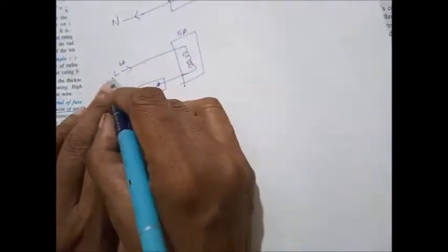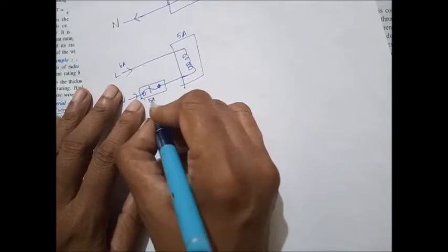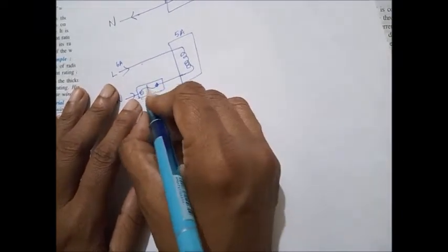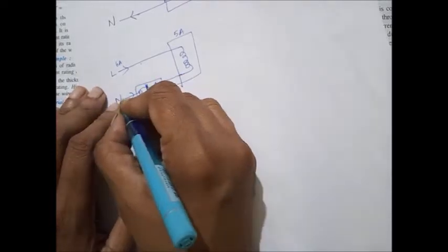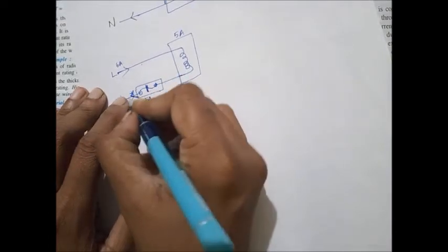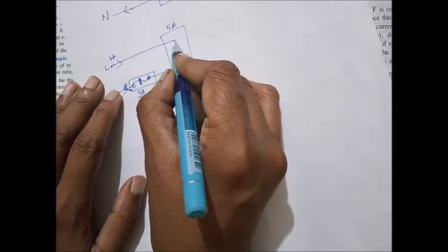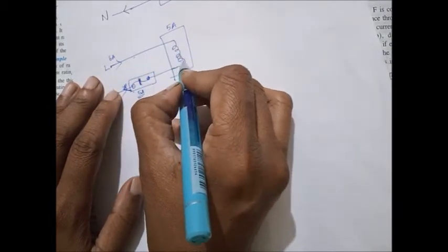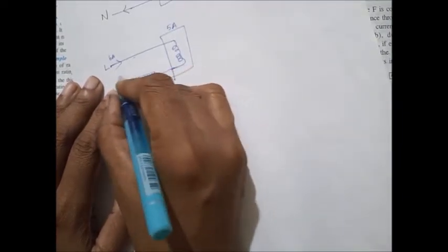So as usual, if its current rating is 5 amp and one day 6 ampere current is coming, a high current comes and this fuse wire will melt, because this fuse wire can withstand only current till 5 ampere. So in this path there will be an open circuit. Current enters through this and comes out through this, but there is an opening. So can the current flow even though the fuse melts? Will the current flow?